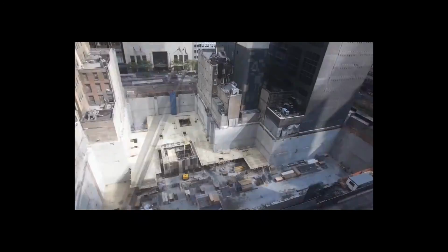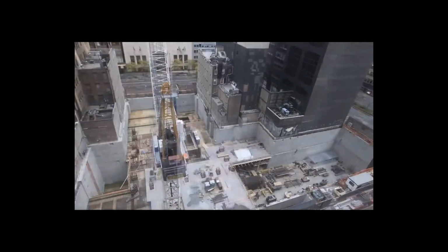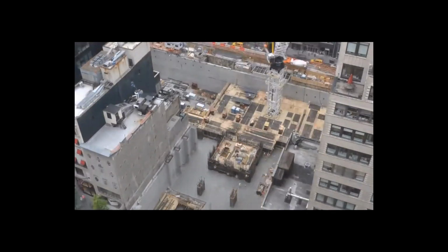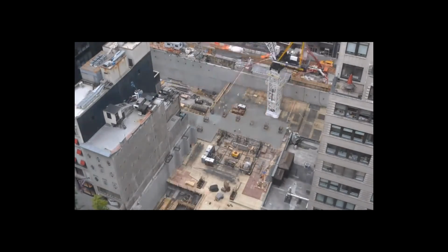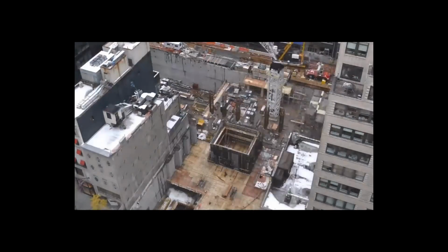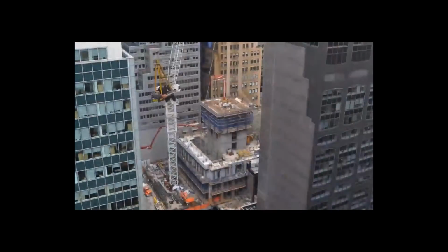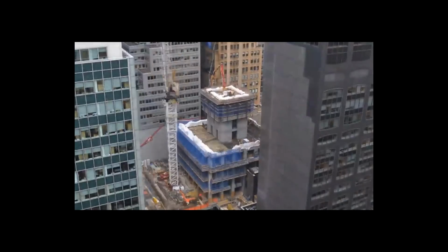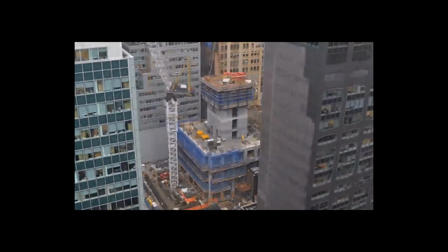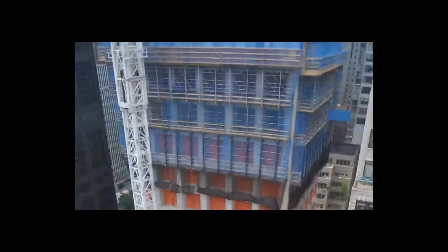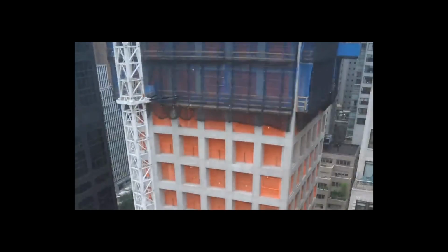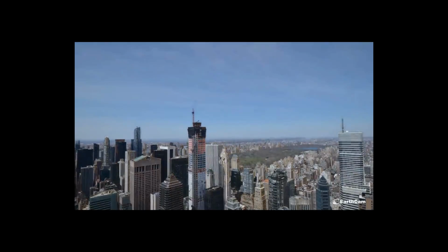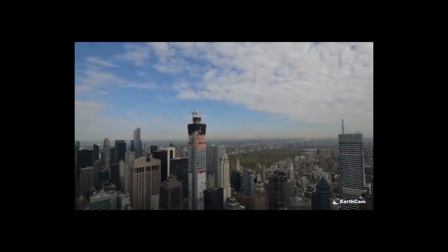The construction process of the reinforced concrete core and frame took 3 years. Firstly, a timber formwork was placed starting from the ground level. Then steel rebars were installed and the concrete was poured in the formwork. The regular repeating geometry of the tower allowed the slip forming to be used. The formwork was customized for the scheme. It includes 4 working levels and storage capacity for the next floor up to improve efficiency. This allowed to cut the labor by half, making it a safer site with less people working there.